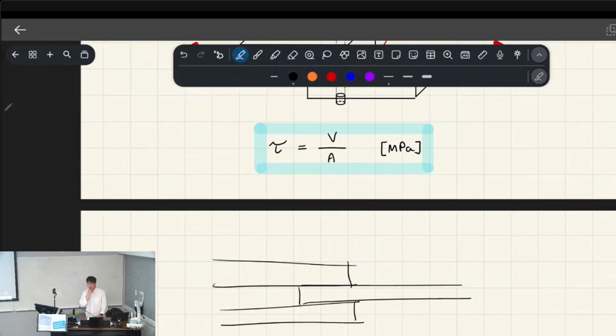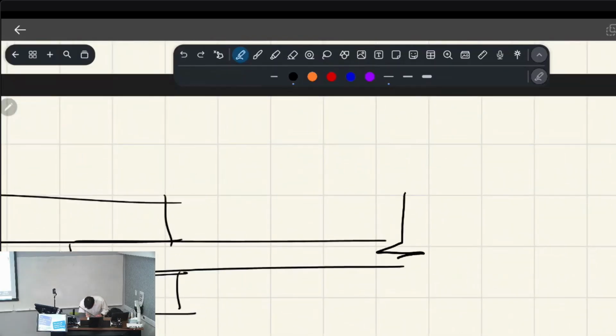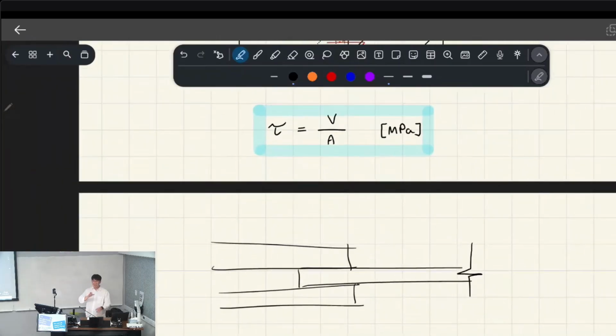By the way, have you guys seen a line break before? You might have seen this, or you might not have, but this is super common in engineering drawings, which is what we in Australia call blueprints, basically. So in engineering drawings, you'll see this thing. Looks like that. And it means that's the end of my drawing. That's it, but it keeps going. Do you know what I mean? So it's to indicate that it doesn't become a floating mess off the screen. You know, you might do, for example, and this is a stylistic choice.